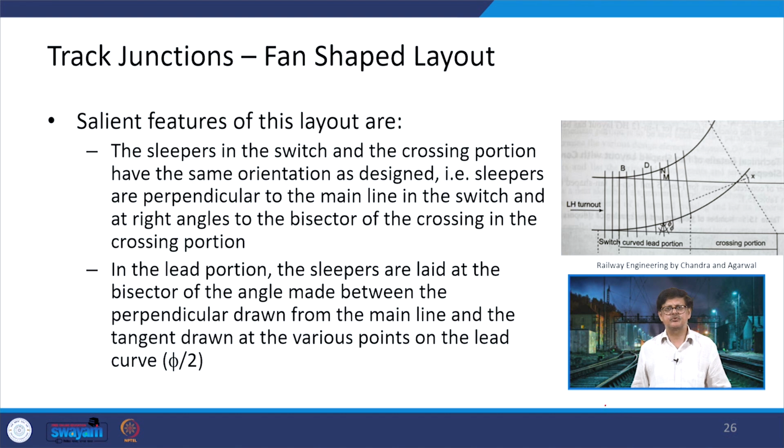The sleepers in the switches and the crossing portions have the same orientation as designed. The sleepers are perpendicular to the main line in the switch and at right angles to the bisector of the crossings in the crossing portion. So, when you talk about this crossing, it is at the bisector of the crossing.